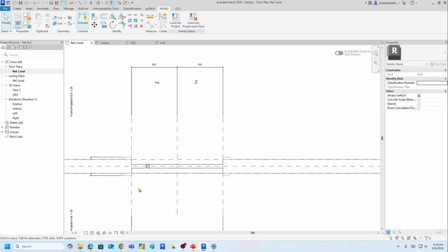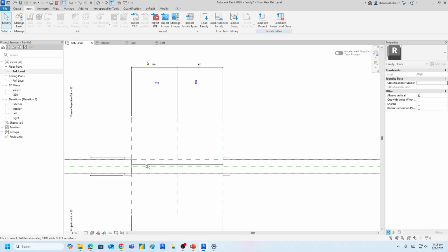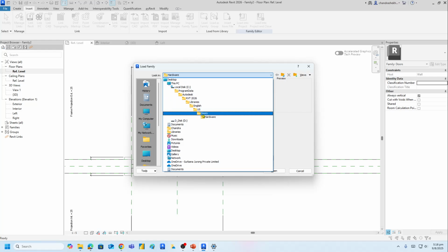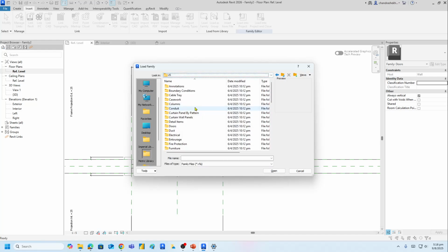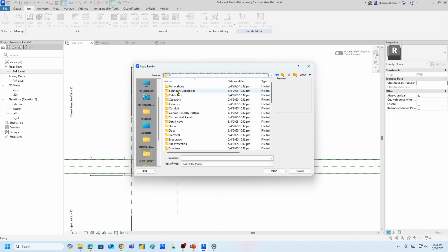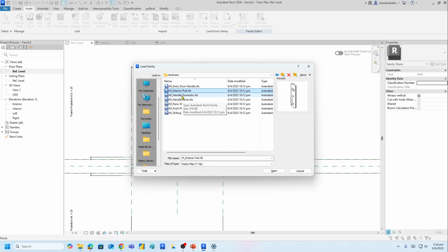To put a door handle, we have to load that handle instead of drawing it using all these create commands. Somebody has already done it. So let's put it. I go to the insert family here, load family, and look at the different kinds of door handles. I have installed US, and in the US I have both metric and English, and the other one is Imperial libraries. So I'll look under the metric library, under the doors, the hardware, under door pull.